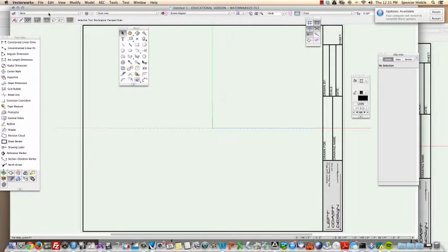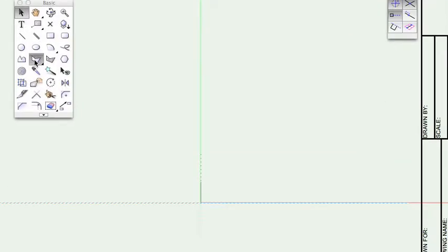Alright, so we're in the class of none. I hate to pound on this, but we're in the front view. We are in, and none is use at creation, and we're in front view over here. Okay, here we go. Polygon Tool. I'm going to click right there at the center, and I'm going to drag across, and I'm going to hit the tab key to get me inside that little dialog box there, and I'm going to put in 4 inches. I can see it's at 180 degrees. That's good. That means I'm horizontal. And it also means that I could draw anywhere within this circle here that I wanted. All right, but I want to be at 180 degrees.